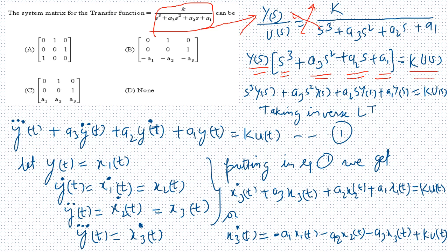Now what we are trying to do here is develop a time domain system. So for developing a time domain system, we need to convert this into the time domain. First we multiply by y of s inside the bracket, and then we take the inverse Laplace transform and use the property of differentiation of Laplace transform.